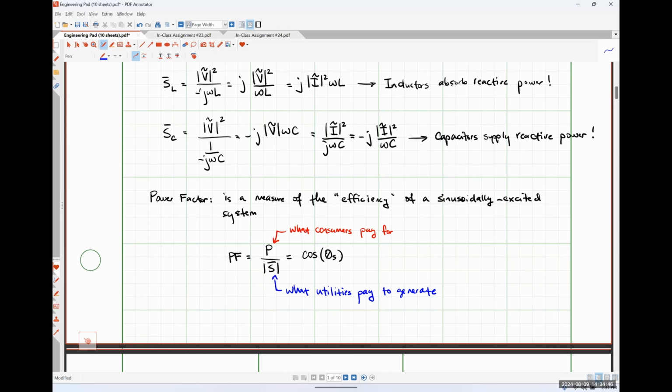But at a large scale manufacturing plant, where you might have several induction motors being used to power conveyor belts, large air moving fans, compressors in multiple HVAC units, things like that, you tend to have a larger inductive load on those systems, which causes those manufacturing plants to operate at a lower power factor, and that is expensive for the electric utility to maintain, and they pass that cost off to the manufacturing plant in the form of fines.